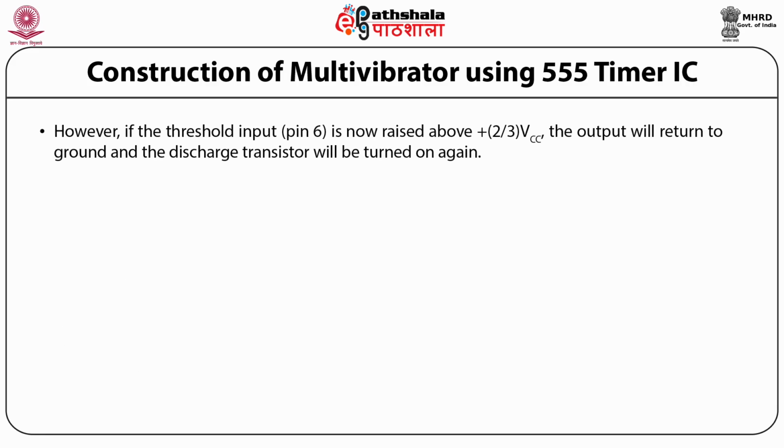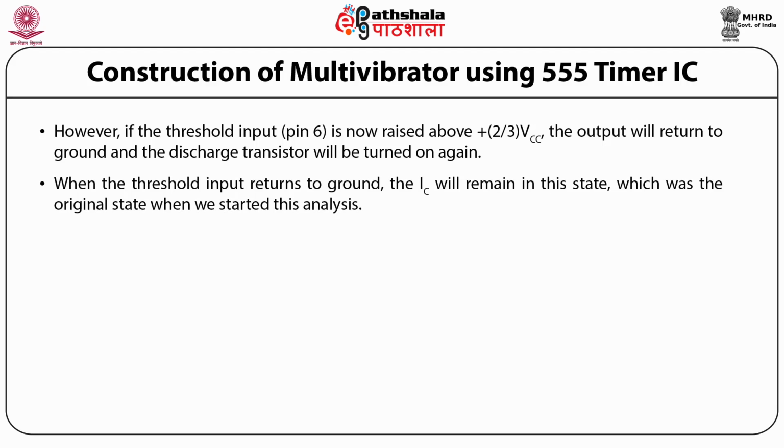However, if the threshold input, pin 6, is now raised above 2/3 VCC, the output will return to ground and the discharge transistor will be turned on again. When the threshold input returns to ground, the IC will remain in this state, which was the original state when we started this analysis.